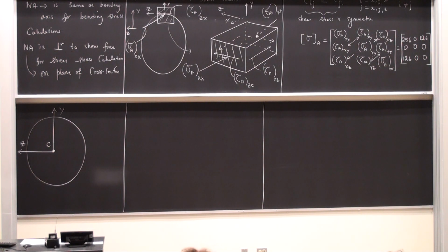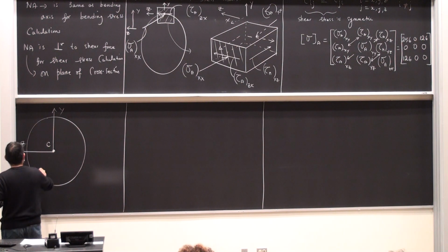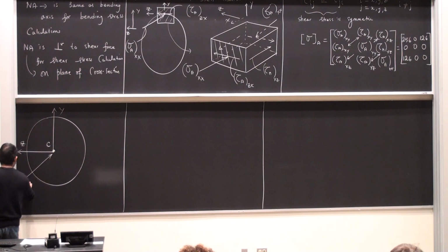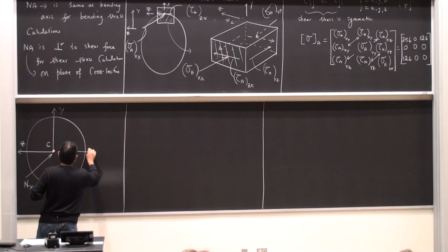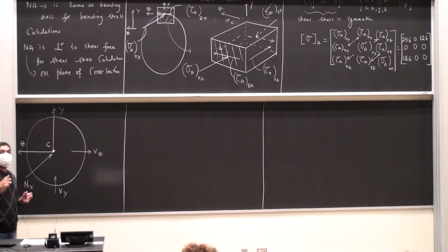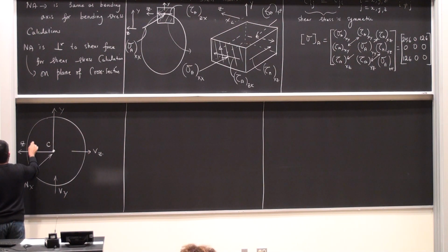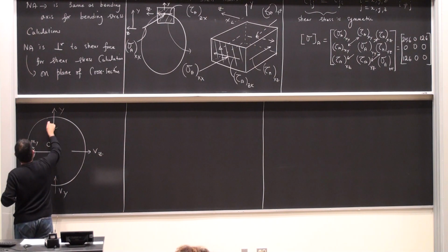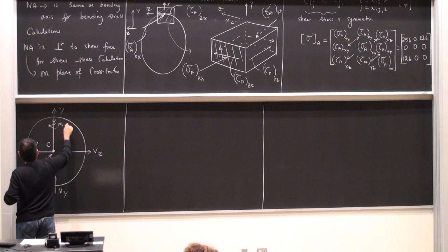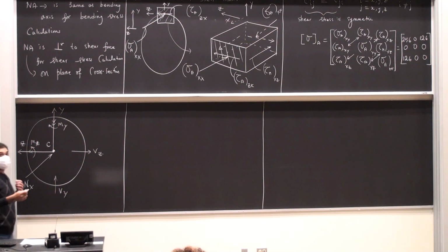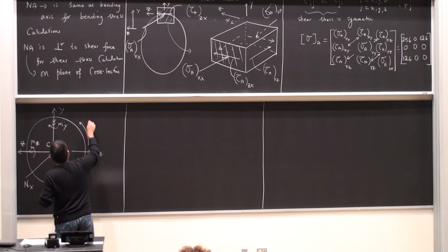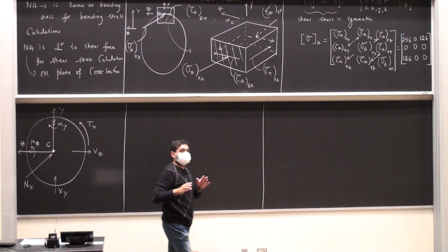I have the following forces, torque and normal forces acting on it. So once again, normal force in X. Okay, then I have VZ and VY. Bending moments, MY and MZ. And then the torque, Tx. Now let's start whittling it down one by one.